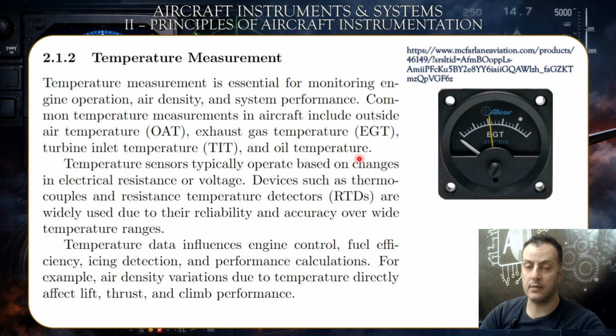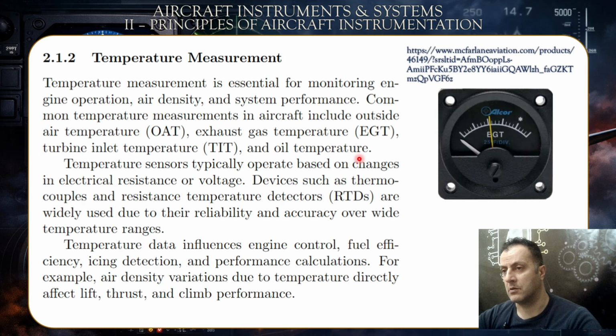If it's overheated, we might be suffering from an overheat of the engine, and the engine might have a big problem, okay. So if you have an overheat of the oil, it means that there's no cooling within the engine, or there's a big problem developing, depending on the scenario. So mainly the temperature of the oil should be nominal. The temperature of the EGT, exhaust gas temperature, also should be nominal. If we are going above specific limits, it means that the engine is overheating, okay? And a bigger, more serious problem can be developing on the inside.